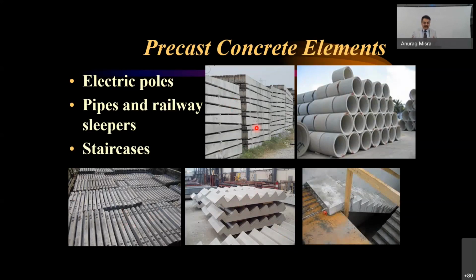Now, when you are going for precast concrete residential units, even the wall panels are precast, and don't think that it takes huge time. They use bigger pallets, maybe 4 meter by 8 meter, and the outer lines are drawn with the help of a robotic arm.